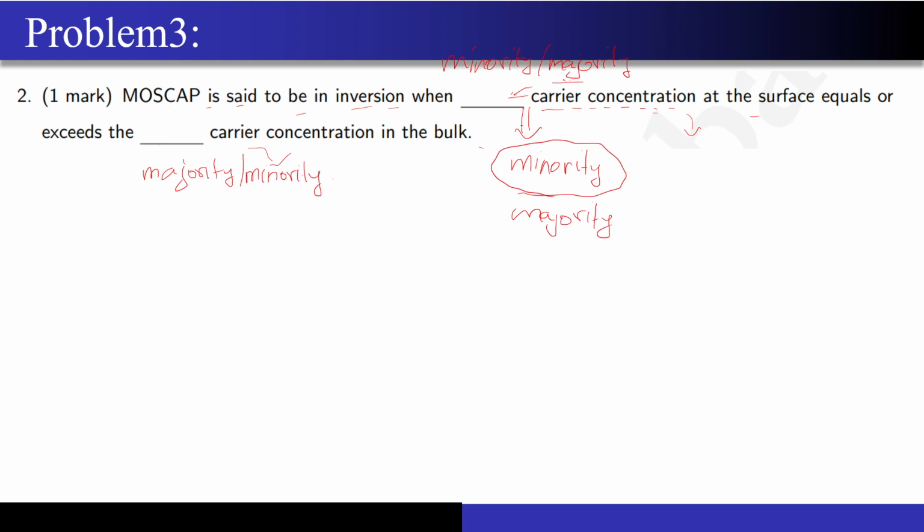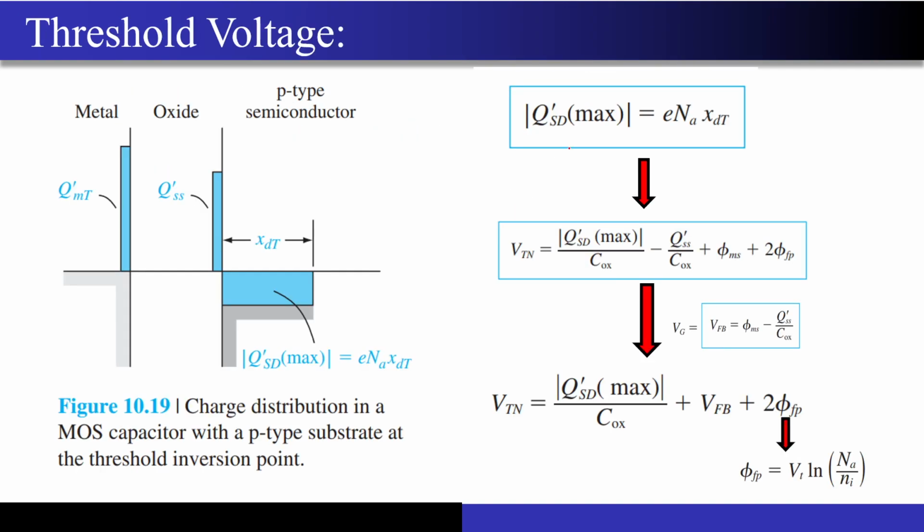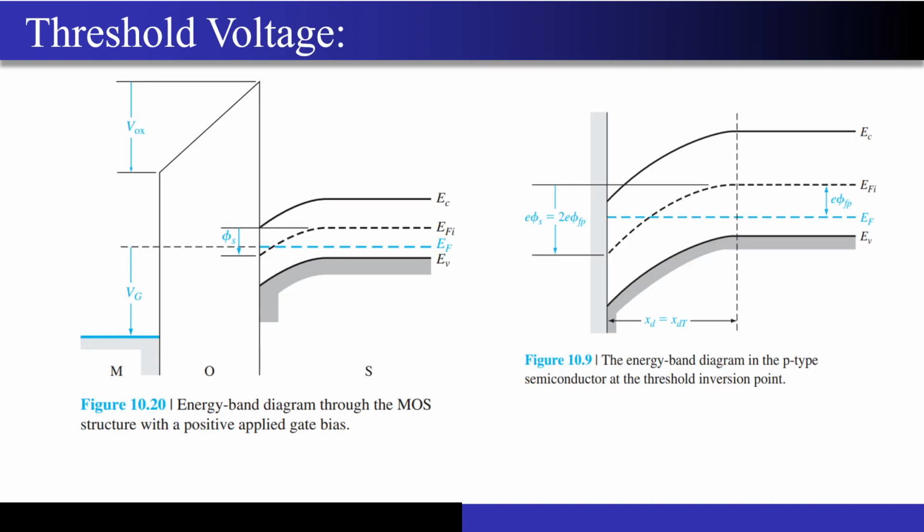So he said that these are the minority carriers, and let's see the reason for the same. See, this was, I already told you, your P-type semiconductor material. I already told you how to differentiate between P-type and N-type. The moment you have a Fermi level in the bottom half, between EFI and EV, you consider this a P-type semiconductor material, and the moment you have a Fermi level present in the top half, then your semiconductor material is N-type.